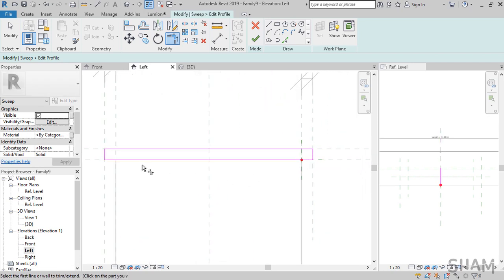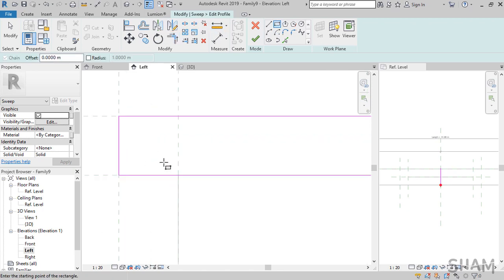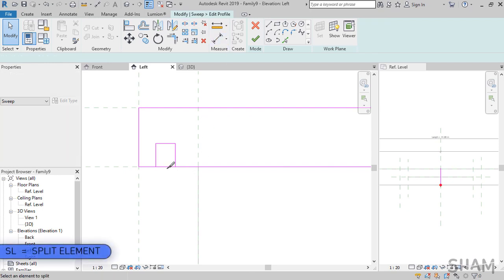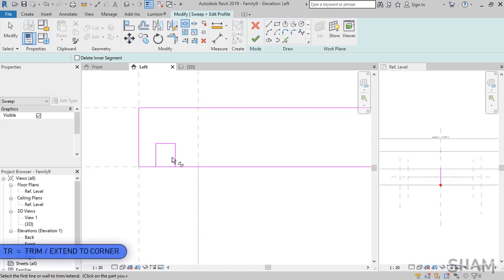And let's add a water canal to the tiles to protect the beam from rain. Use rectangle to create that. Zoom into the tiles and simply create the rectangle like so. Let's delete part of the rectangle from this side, and from the Modify panel use the Split Element, more like split line, it goes with the shortcut. Slice this line and next use trim to clean the part.